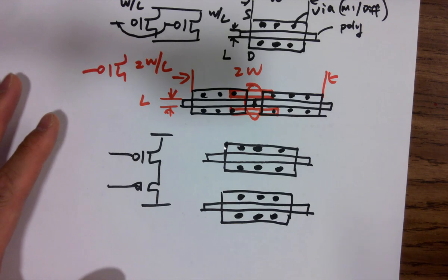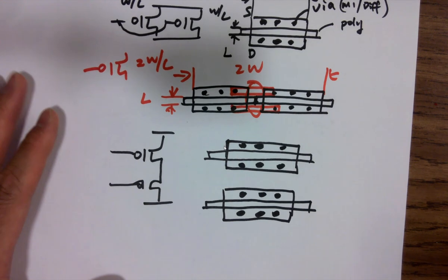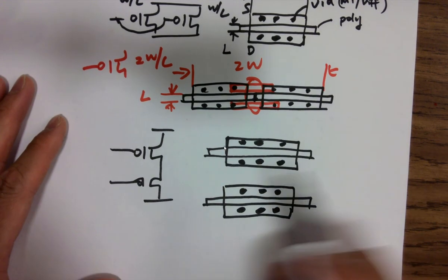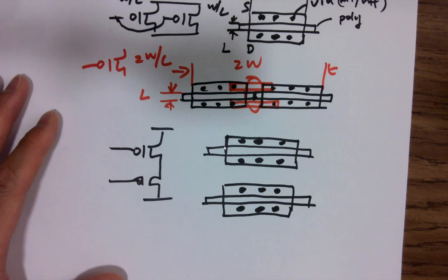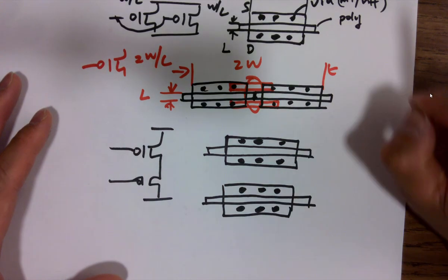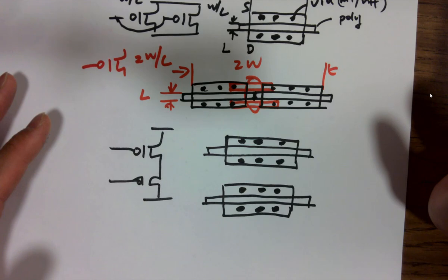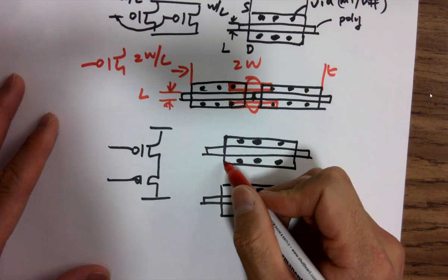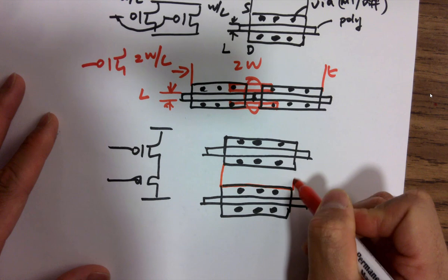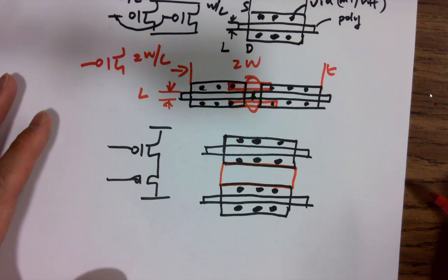How do we connect them? Do you need to connect the poly? Actually, no, because they're not shorted. It would just be the drain to the source. So it would just be a single metal connection through the vias on the two inside. Metal what? Yeah, just metal one. Grab a piece of metal one to make the connection.